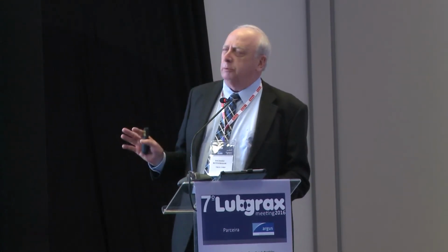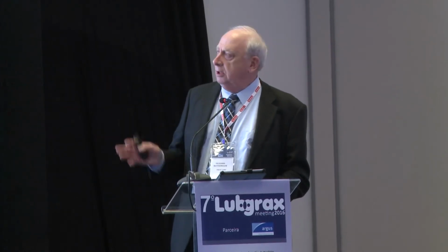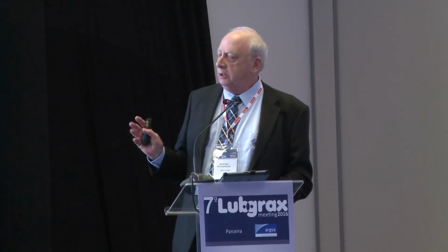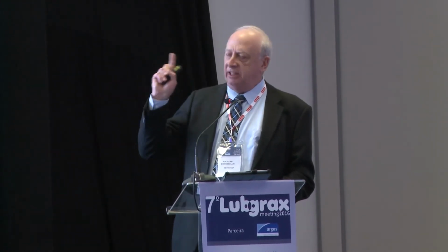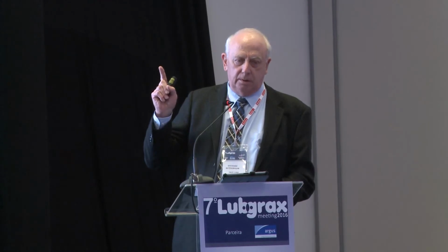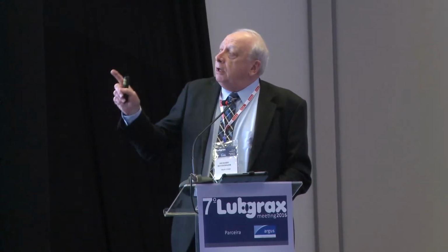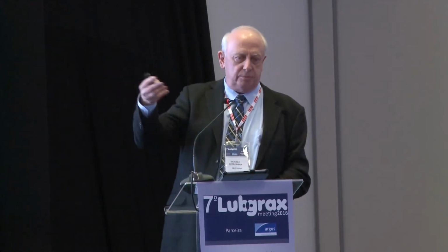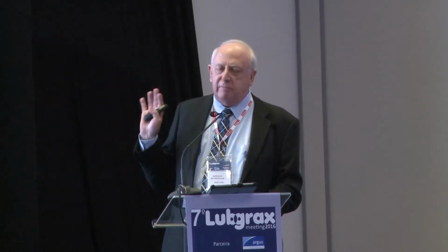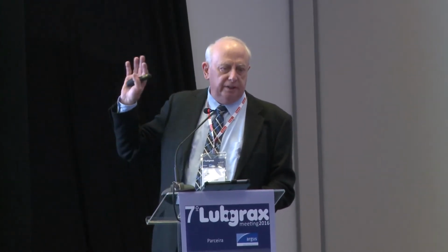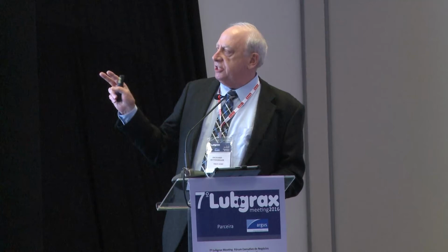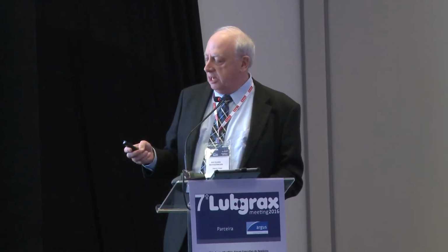There is certainly a global trend of end users saying they want fluids that need no tank-side maintenance or minimal tank-side maintenance. One of the major US automakers considers any additions, not just biocides, but any additions to a fluid to be a fluid failure. So very strict requirements. And we see that in the fluids that we get from our customers to evaluate, to make sure that the biocide package is effective. Modern fluids are dramatically more bioresistant than the fluids from even the 1980s. So the fluid selection by the customer has a huge impact on the fluid management requirements and fluid life.